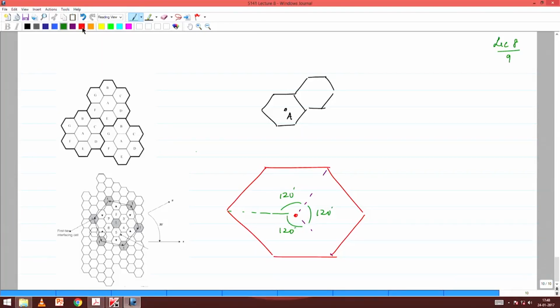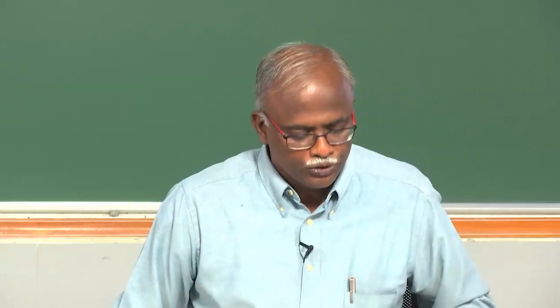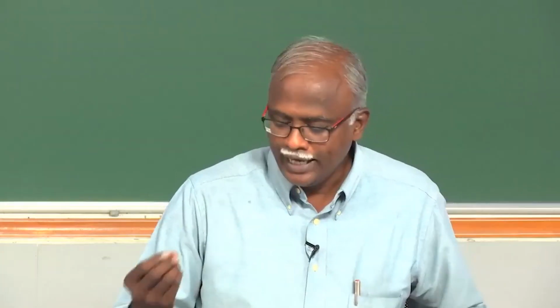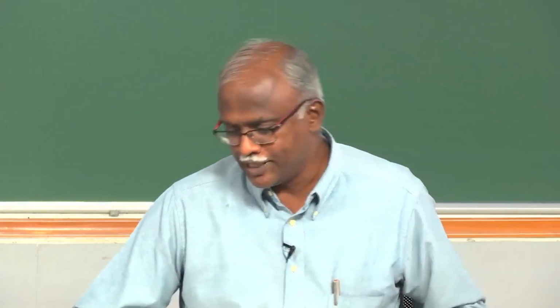The other way to implement a 120 degree sector is another elegant solution, and you may almost say that this is the reason why we have chosen a hexagonal pattern: move the base station from the center of the hexagon to a vertex. Automatically you get 120 degree sectorization. So for many reasons hexagons are the preferred choice, and in the next lecture we will introduce the elements of a hexagonal cell geometry based design.